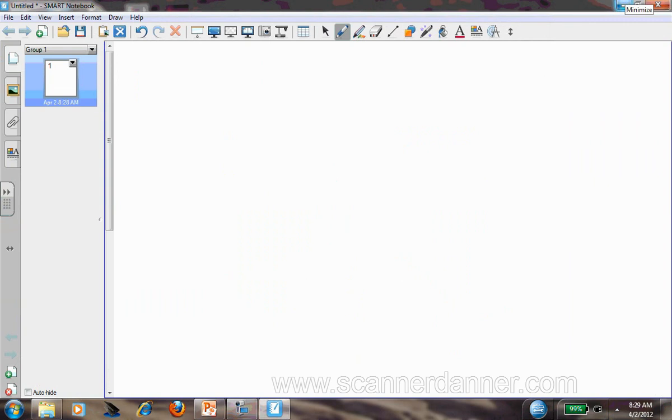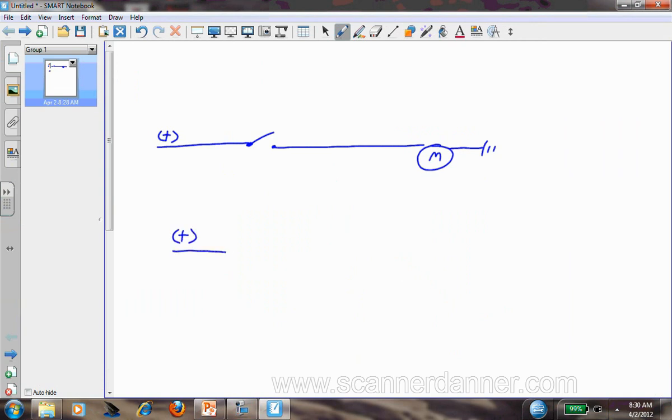An older car may have a door lock circuit like this, where the switch directly controls the motor. I know it's not like this because they use reverse polarity. So I'm not being technical in the drawing, because this one is obviously switched on the power side all the time. That's not the way door locks work, but this will give you an idea of what I'm talking about. So that switch is directly controlling that motor in this picture. On a switch input design, to compare, you would have a switch that's going to go into a computer, some type of computer, whether it's a body computer, engine computer, whatever.